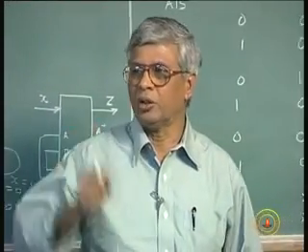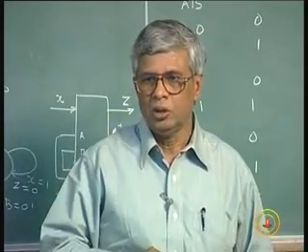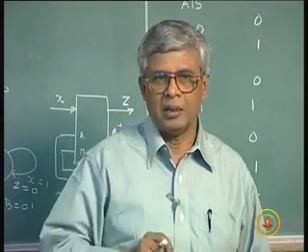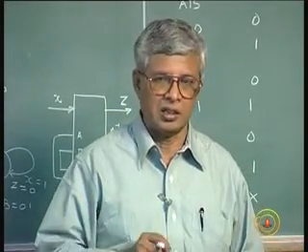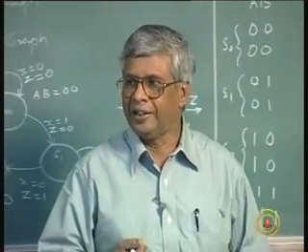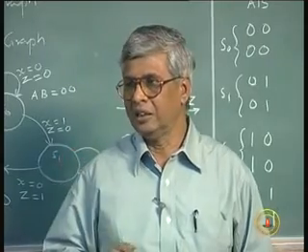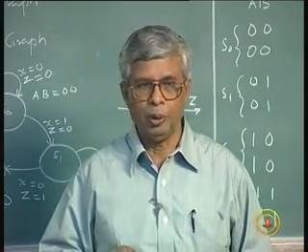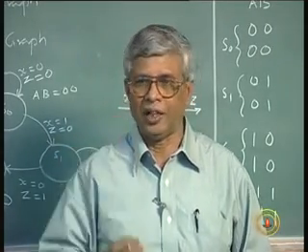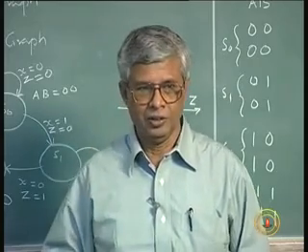Make the output 0, so that if by chance the circuit happens to be in that state because of transients when you switch on the power for the first time, I don't want any output in that state because I don't want a glitch in the output. That output may control a lamp or a traffic light, it may be a green light, and I don't want a green glitch.